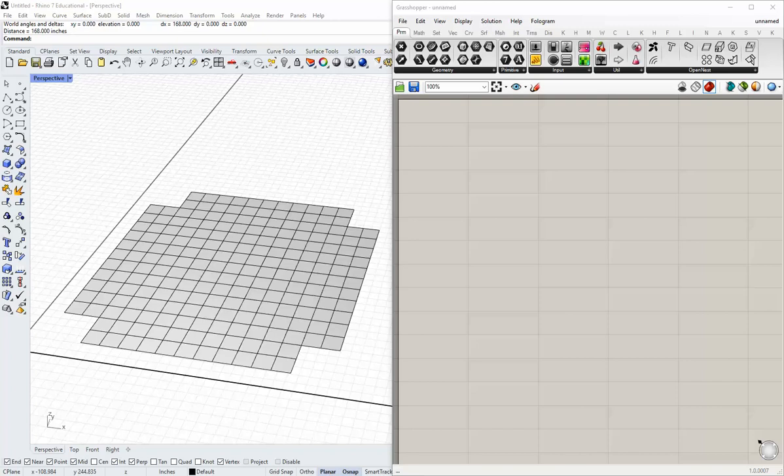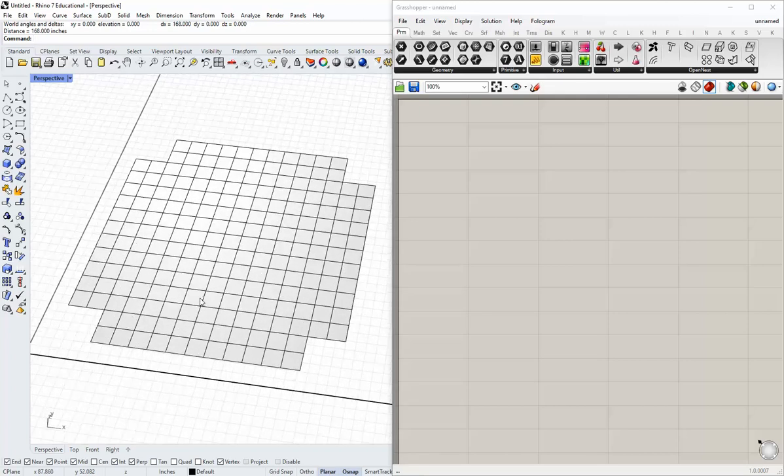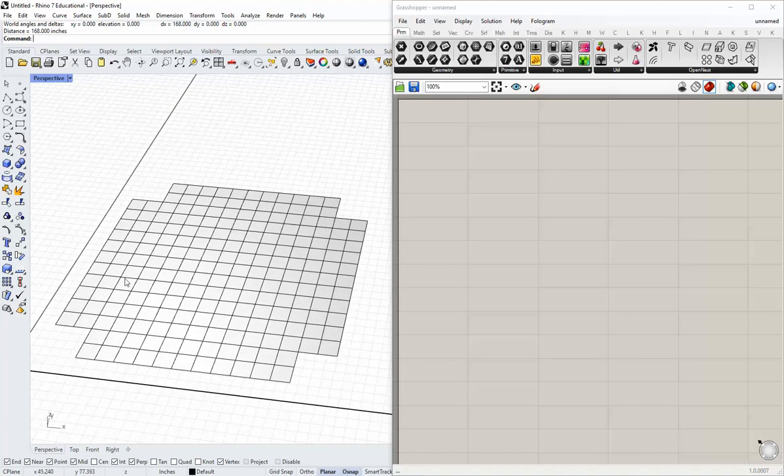Okay, we're going to get started on part one of our final semester project. This will be the initial form finding phase, so you all have a Rhino model, and it has the base mesh that we'll start with. This is a mesh that's around 14 foot square, and it's broken down into 15 faces in one direction and 15 faces in the other.